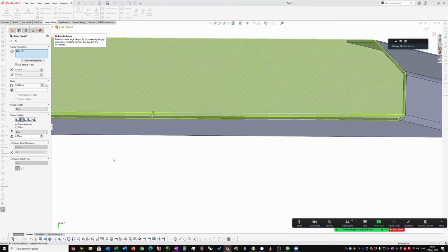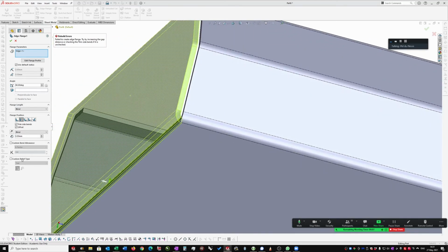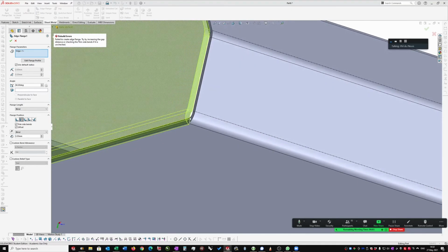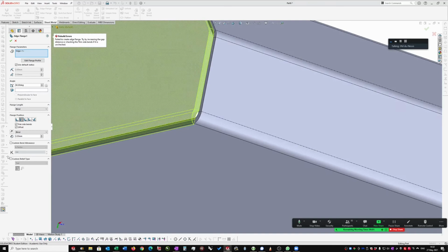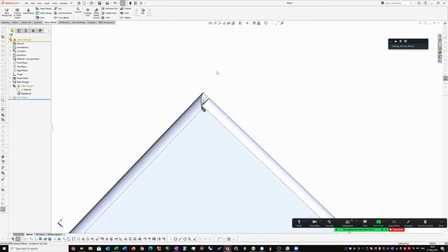Oh, right, okay, so the problem here is, if you have a look here, you can see that because I've got the custom relief type as a tear, and this is the reason why I actually pulled it in, that's going to be a problem. I think this is the problem. Let me just make sure. If we go to an OB round and give it something like that, there we go. Alright, so this should be better. There we go, it's done it.